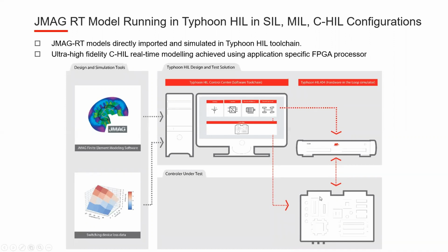Then we plug the controller into this system. So then the controller actually doesn't know that it's controlling the simulation instead of the real plant, as we said already. And then we can play around, see what's going on, improve our code, test, and so on.